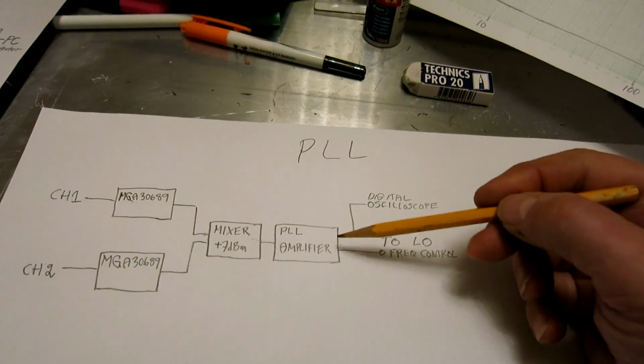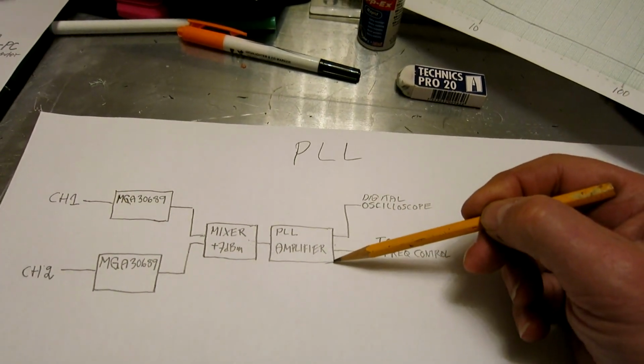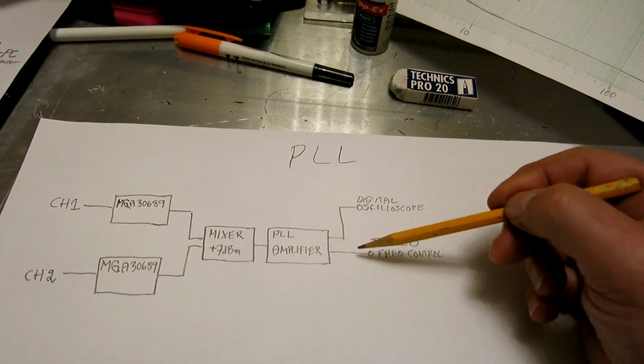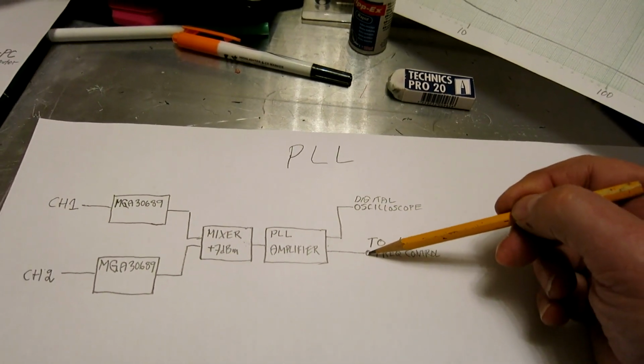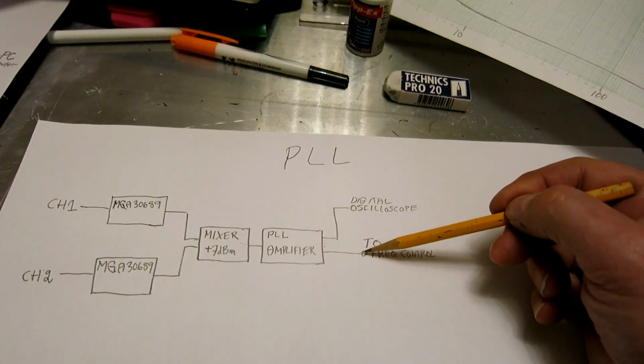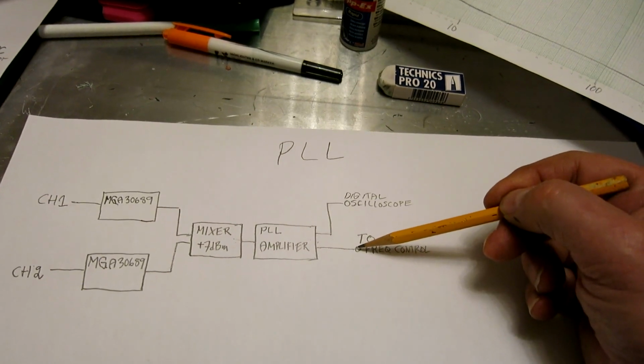And it's necessary to set a large time constant in order to do measurements close to the carrier, because otherwise the PLL is going to lock the oscillators and transfer the modulation on one to modulation on the other.